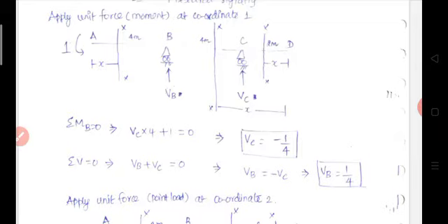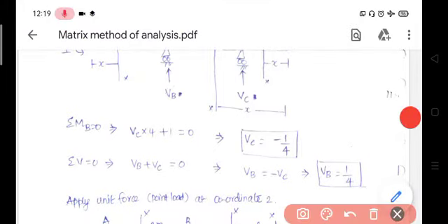In both cases we have to determine the moment for AB, BC and CD portions, and the origins are the same. Okay. So, that is why it seems correct. So, first for the AB portion we consider section xx, which is x distance from A. Therefore, the limit for the AB portion is 0 to 4.